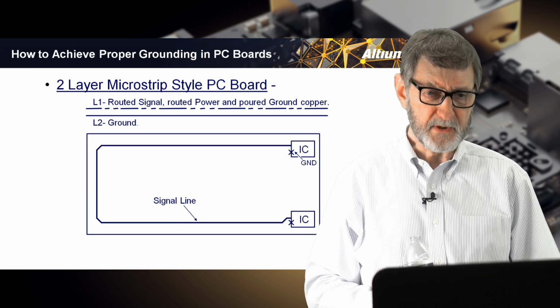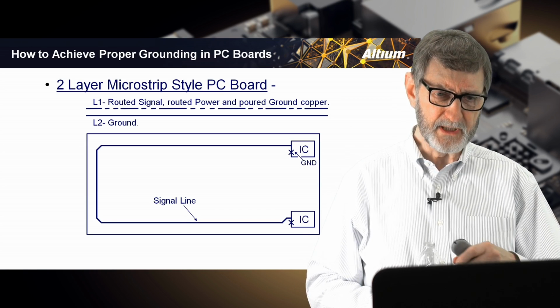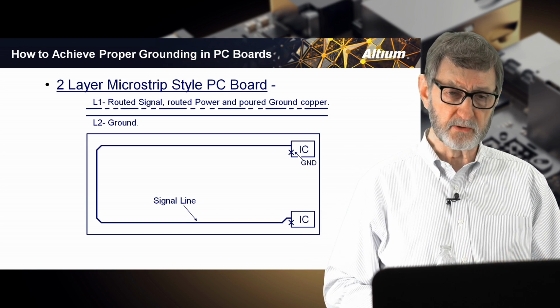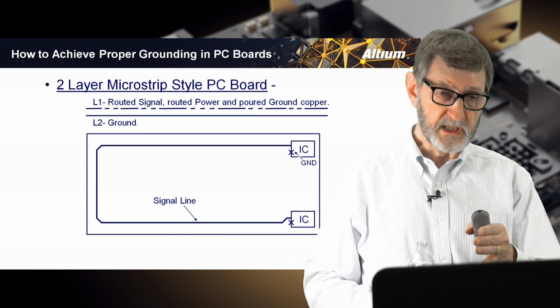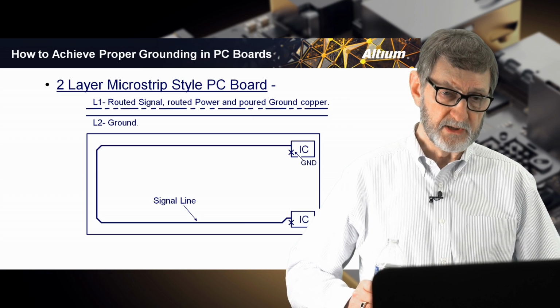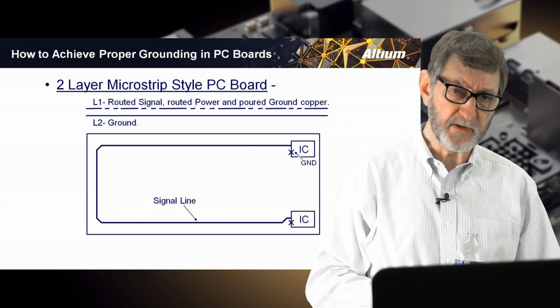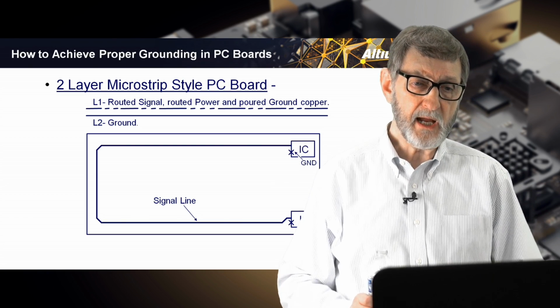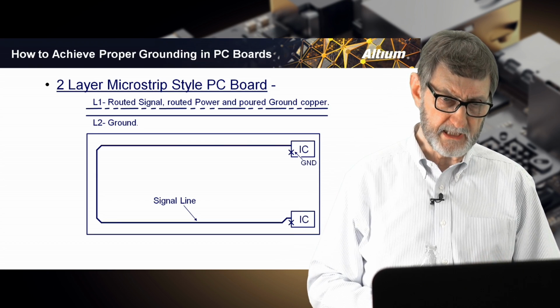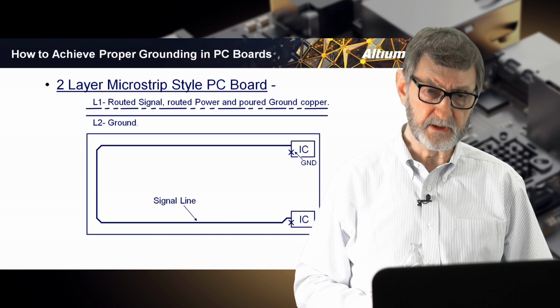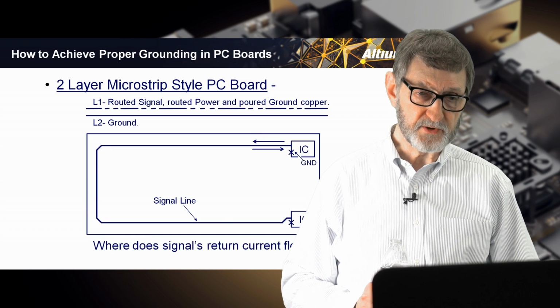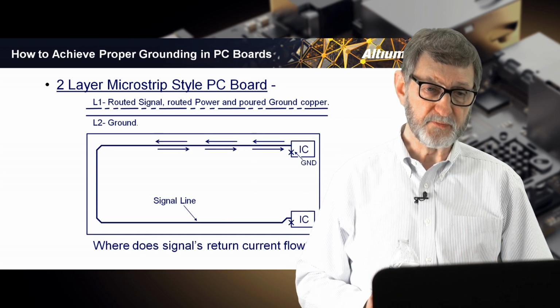But as you go up in frequency, into the 200 to 300 hertz range, the energy would be more focused toward the transmission line. You go up to a kilohertz, 2, 3, 5, 10 kilohertz. By the time we are out of the audio range, all of the return current in this particular circuit would be directly under the trace following the forward current.